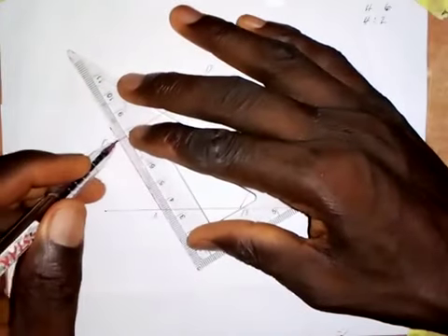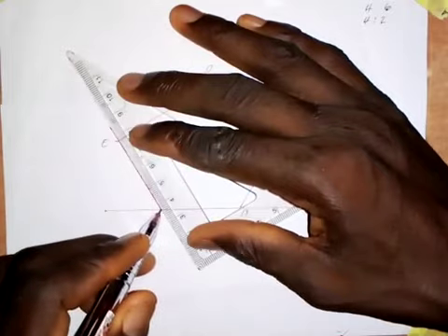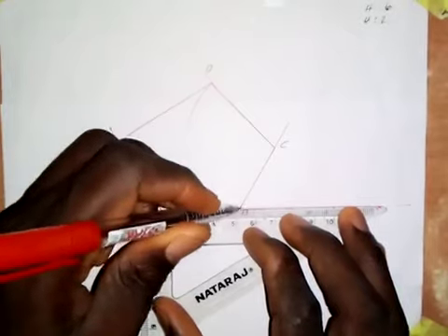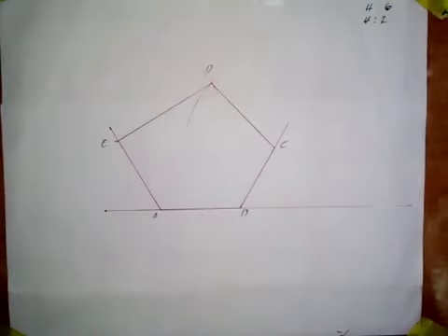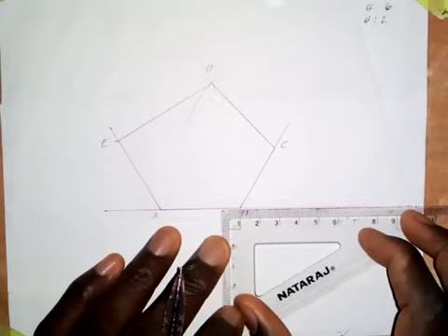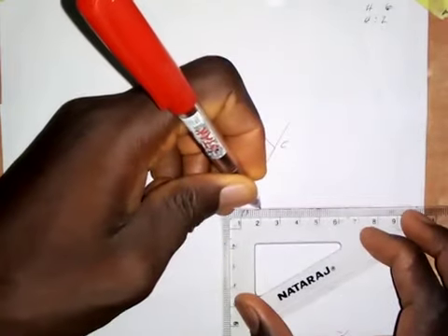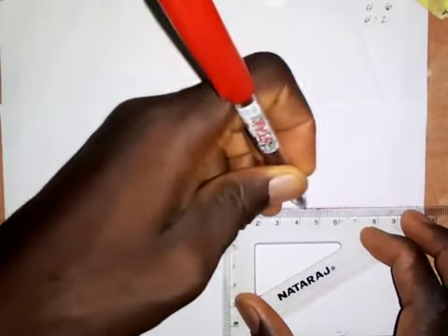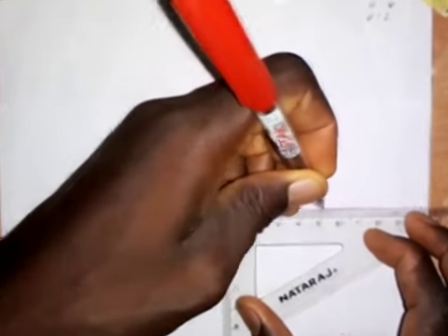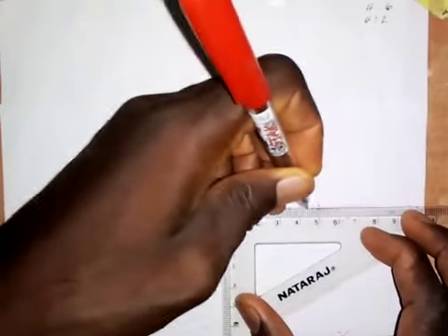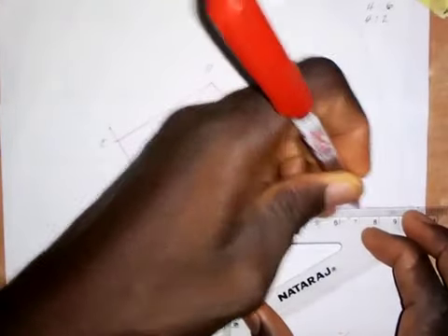The next thing that we are going to do is to go on with the enlargement and reduction. I want to make these lines more visible, so that's why I'm drawing this. Now that we have the polygon in place, what we need to do is to locate 6 points on this line. The highest value of the ratios that we have for enlargement and reduction is 6, since we have 4:6 and 4:2. So we make 6 points here: 1, 2, 3, 4, the 5th one and the 6th one.